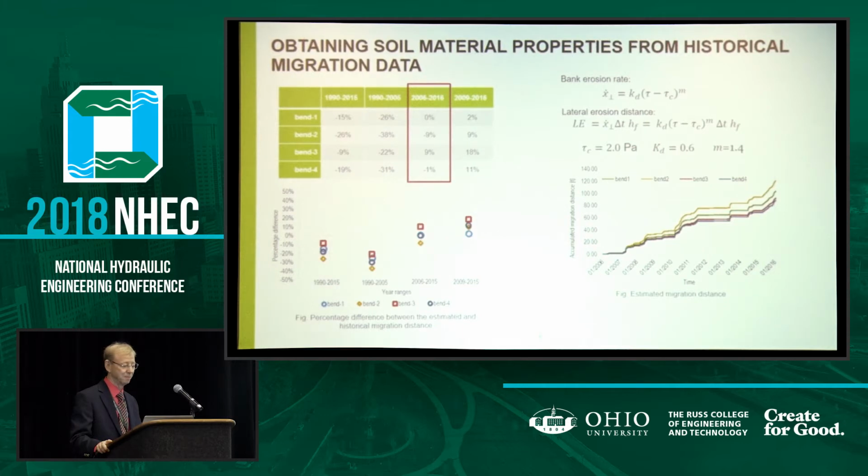And we then can get the flow duration from a hydrograph, and we have to interpolate in our table of shear stresses to get the shear stress for, in our case, a particular day. So we were doing this day by day, and we get a half inch or something of bank migration in a particular day, and if you have higher flows, might be more, and then you just sum those up over time.